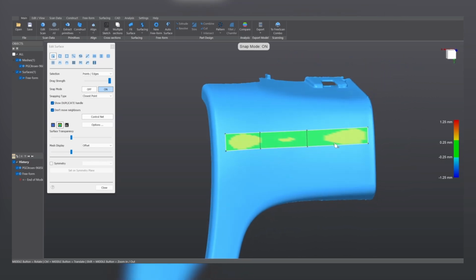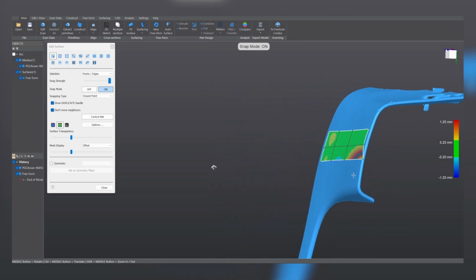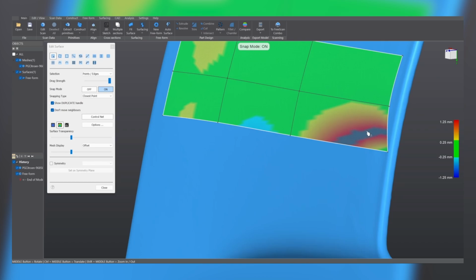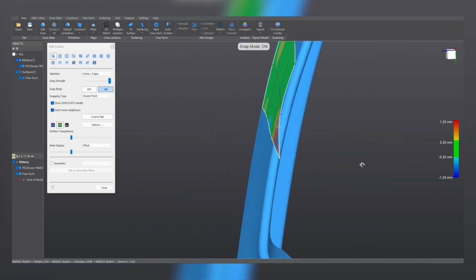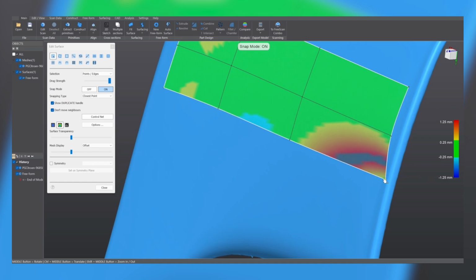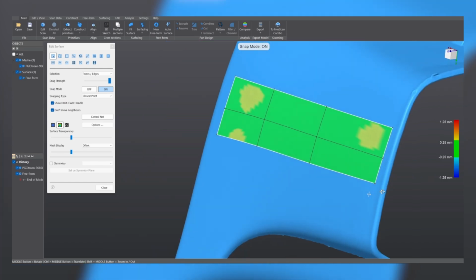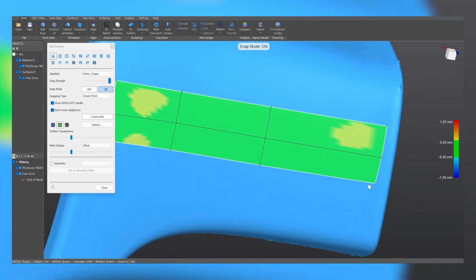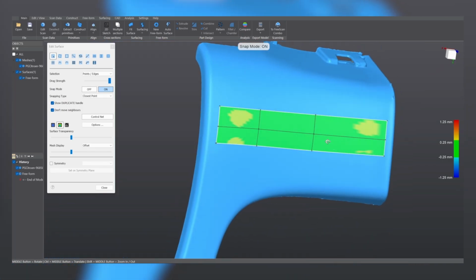To extend an edge, you can double click on it. It turns yellow, and then with the D handle, you can extend the surface. Now, if you observe some unexpected high error like this, it's because the surface is snapping on the other side of the mesh. So you can simply correct it by moving it a little bit, and it will snap onto the proper surface.